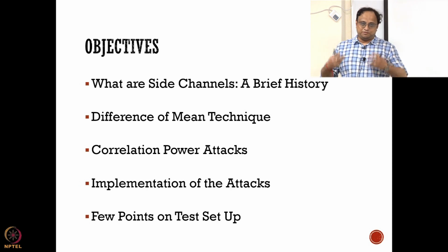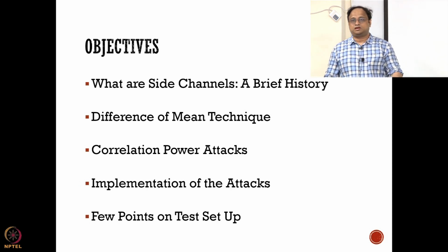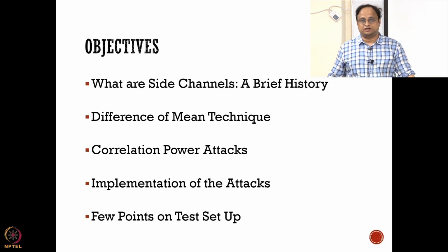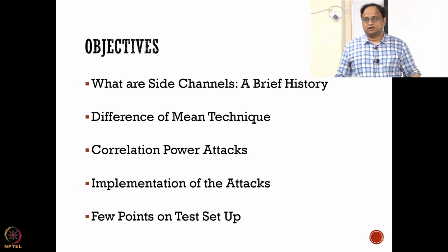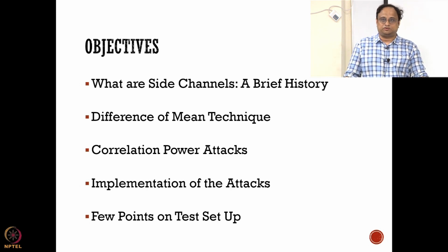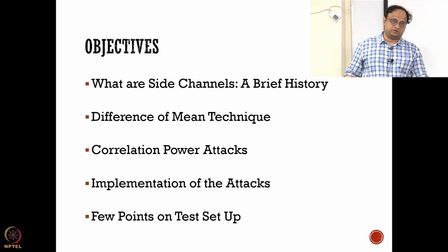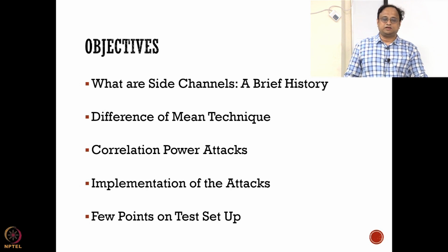If you implement a crypto system on, say, a mobile phone or a credit card, then when the crypto operates, it consumes power. Any computation will consume some amount of power. But the very interesting fact that we will try to understand in today's discourse is that power consumption has a signature of the secret key. And if you know the techniques, then you can utilize that power consumption to do a cryptanalysis which can give you the secret key.